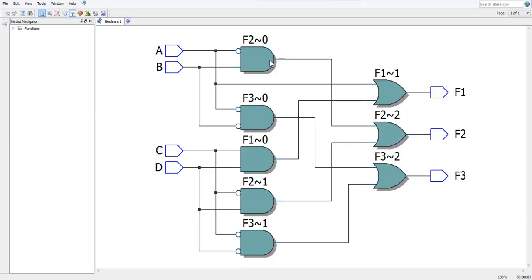Now this is the circuit which was built by Verilog or Quartus in its RTL viewer. This F1 gives out the output for the first function. Here the first input A goes as an OR, and the second input C combined with D goes for the first. Similarly, the not of A goes in the second function. The B simply goes as an AND with the not of A into the second function, and so on. These schematics have been explained in detail in the previous lab.